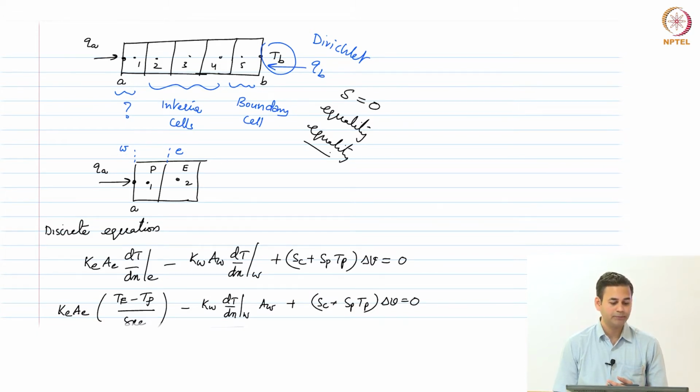So, what you realize is that out of the two Neumann boundary conditions that you have given, there will be one less equation, essentially one of these equations will become dependent on the other one. So, out of the 5 cells you have, up till now you have 5 independent equations for all the 5 cells, then the moment you specify all the heat flux boundary conditions for the problem, you will get a rank deficiency. Essentially, one of the equations out of the 5 will be dependent on the other equations.